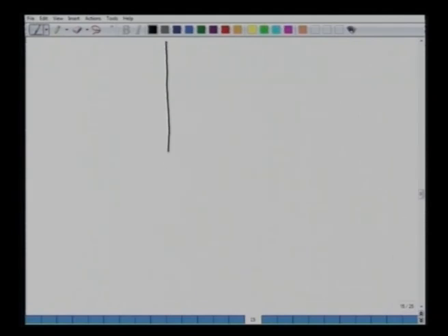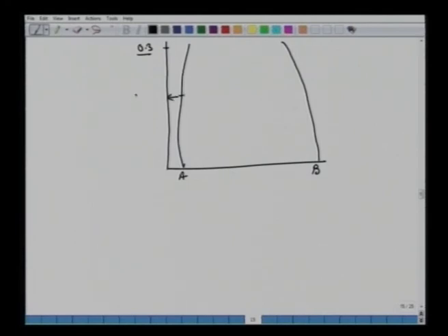After the 3rd stage we had this composition at 0.2. So this was the composition of the raffinate R3 at 0.2. Now we are supposed to use only 1 stage, and we want to bring down the level from 0.3 to 0.2. So all we do is add 1 stage here. The amount of solvent is not known to us, so to find out how much solvent we require, this is 1 fresh solvent, so that the treated stream, this raffinate, contains 0.2.